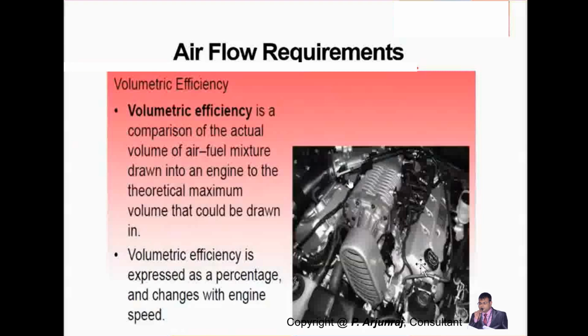such that the air-fuel mixture is optimized, and you are not going for an abnormal kind of combustion where you have only less air and more fuel. If you go for a rich mixture, where you have more fuel and less air, it leads to incomplete combustion. So we need to ensure that we have the proper amount of airflow. We have a stoichiometric mixture, a lean mixture, and a rich mixture. We need to ensure the proper airflow requirement is there for complete combustion to take place.